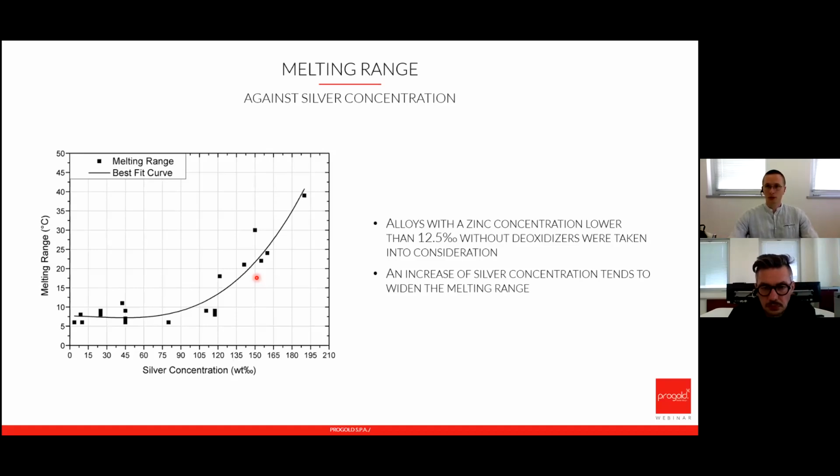If you have a filling problem, for example, you can try increasing the flask temperature or the metal temperature before casting in order to keep the alloy more fluid, so to decrease the viscosity through the temperature. I don't know if I answered the question.